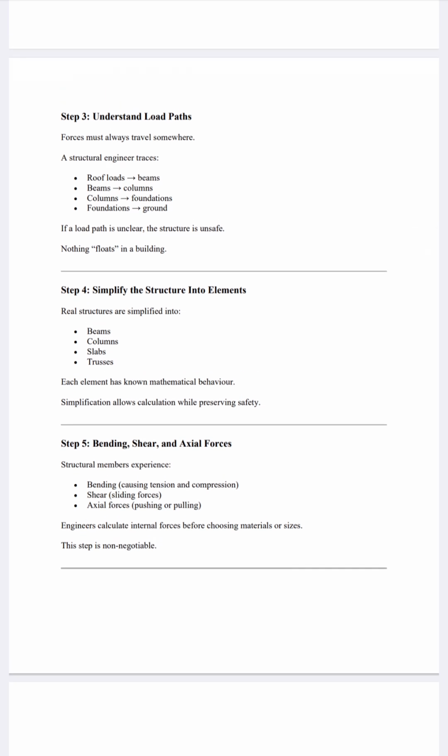In step 3, understanding load paths. Forces must always travel somewhere. A structural engineer traces roof loads to beams, beams to columns, columns to foundations, foundations to the ground. If a load path is unclear, the structure is unsafe. Nothing floats in a building.